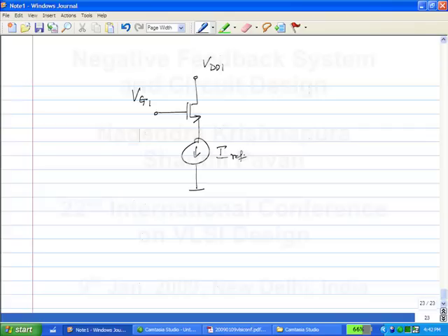And on an IC, transistors are free, but resistors and capacitors are very expensive. On a board, what is happening? Transistors are expensive and resistors are free, right? So if you didn't have to use a current source, what will you do? If you're a poor man and can't afford a current source, what you can do is to recognize the following.